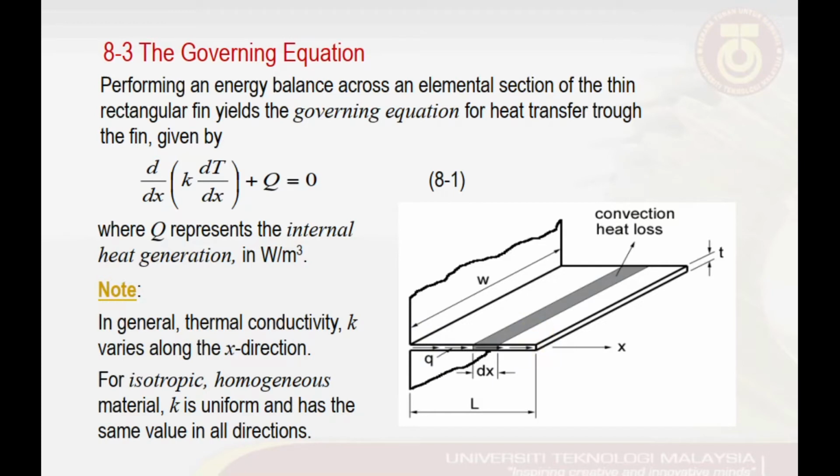Since we are interested in modeling the heat transfer through this fin from the base to the tip, we can develop the finite element model to analyze and predict how the temperature will be distributed from the base to the tip. For a one-dimensional problem, we can discretize this fin from the base to the tip by several finite elements.